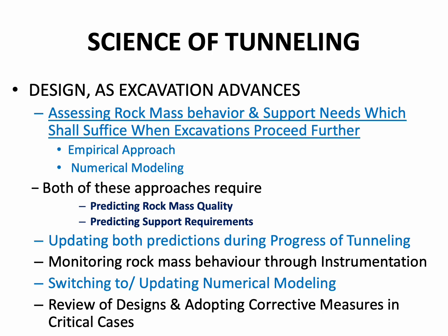Both of these approaches require predicting rock mass quality, predicting support requirements, then updating both predictions during progress of tunneling. That means the rock mass quality prediction is also to be reviewed, and based on that, the predicted support requirements also need to be reviewed during the progress of tunneling.